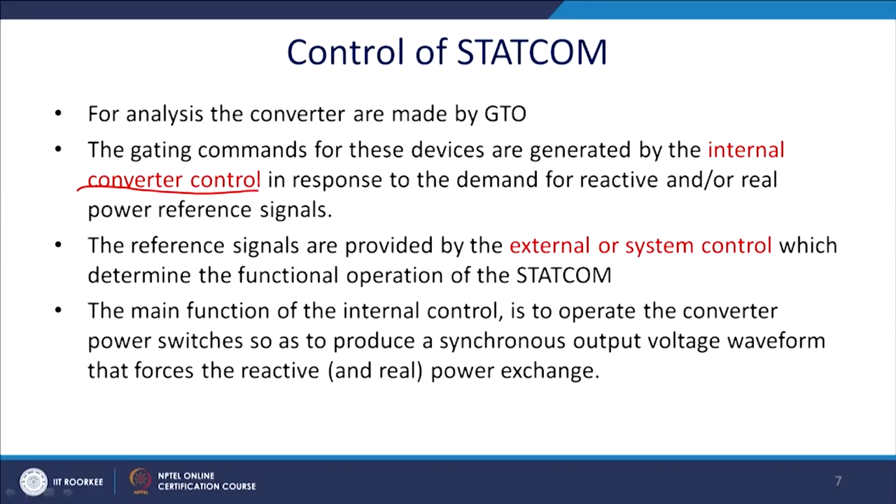The reference signals are provided by the external or the system control, which is determined by the functional operation of the Statcom. The main function of the internal control is to operate the converter power switches so as to produce the synchronous output voltage waveform that forces the reactive and the real power exchange. So, this is actually the way of controlling the Statcom.